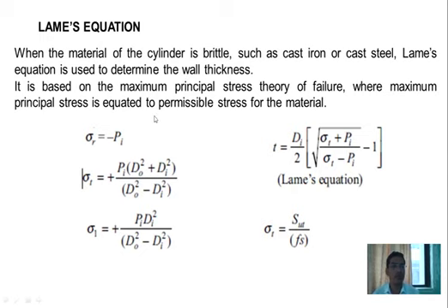Lame's equation is based on the maximum principal stress theory of failure, where the maximum principal stress is equated to the permissible or allowable stress for the material.